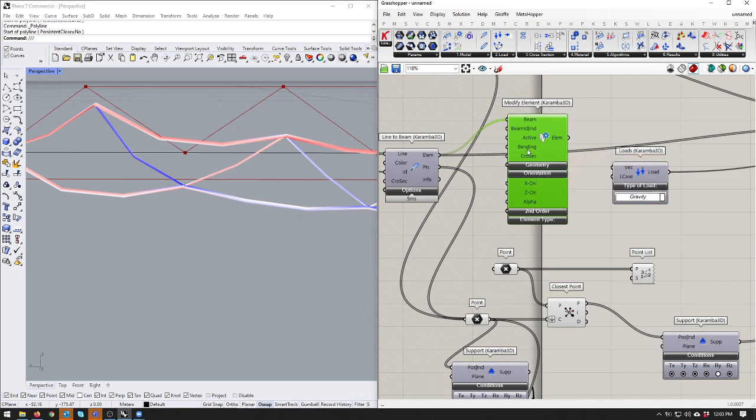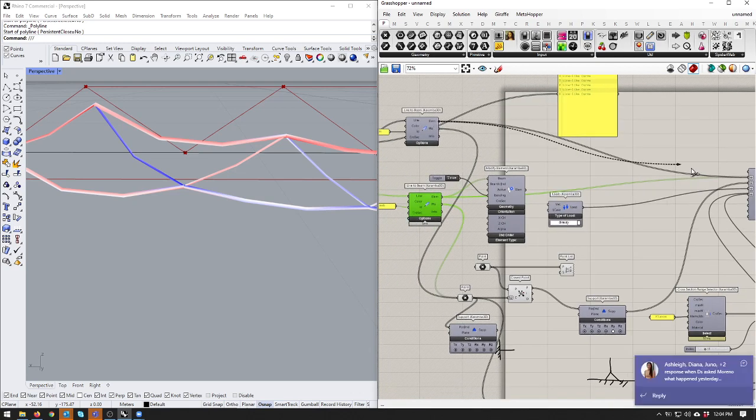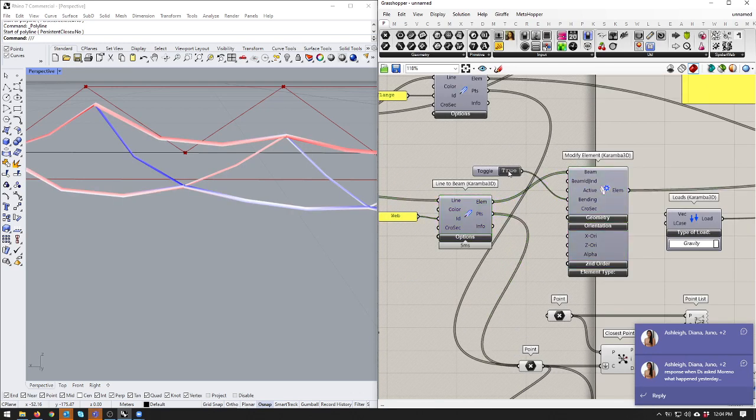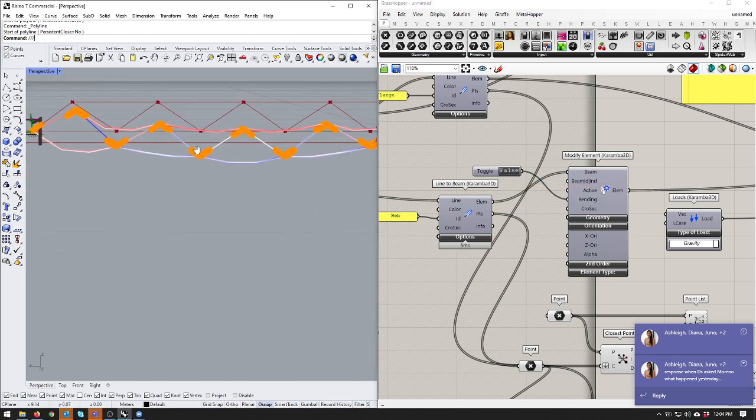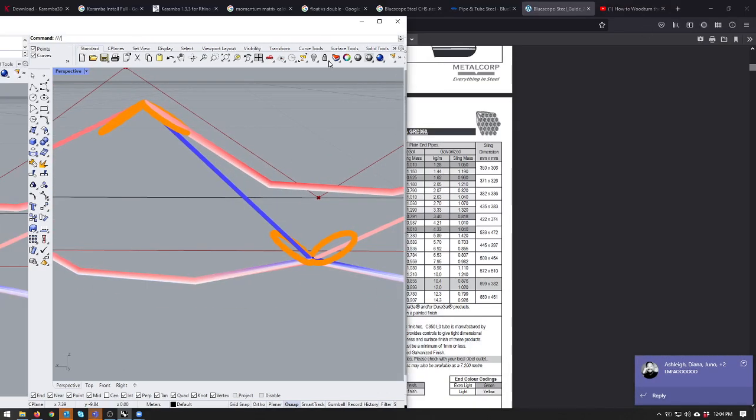There's a bending element. There's a bending input here. If you put a Boolean toggle into that, or any Boolean value, if you're making a complicated script, we can play with that as a true and false. So at the moment we'll set it to true, so it does nothing. If we replace that element and now we turn the bending moment off and on, we can see two things happening to our model.